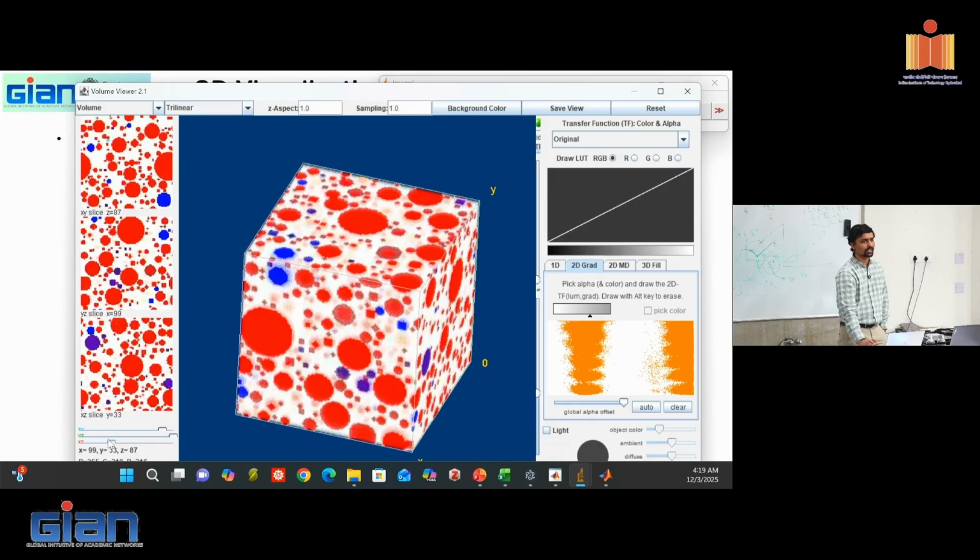But I did not actually define one thing, because there were anhydrides, hydrates, basically gypsum, right? If you put zero for calcium sulfate and all those things, you'll only see red particles, meaning there's only OPC. Because it's very important in the hydration part of it, we have it defined. When I ran this simulation, I just kept the values there for OPC. So hydrates and anhydrides are present. Those are the blue circles that you see there. I think anhydrides are cyan color, not blue. So you'll see two different colors for hydrate and anhydride.